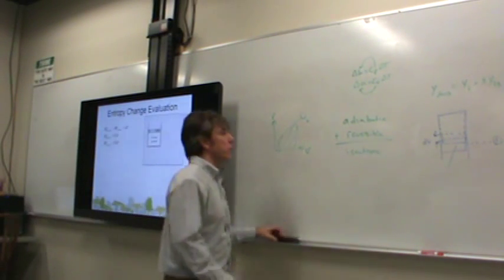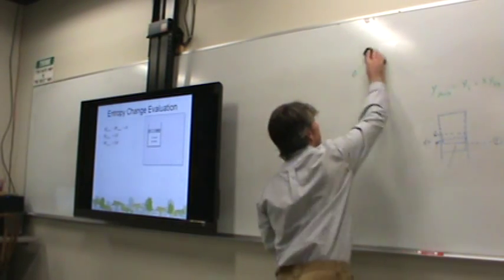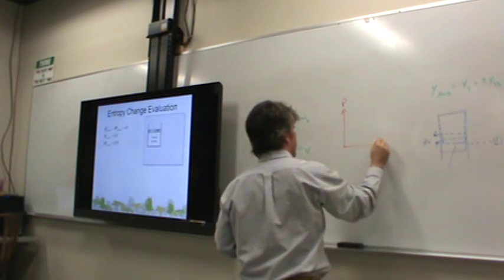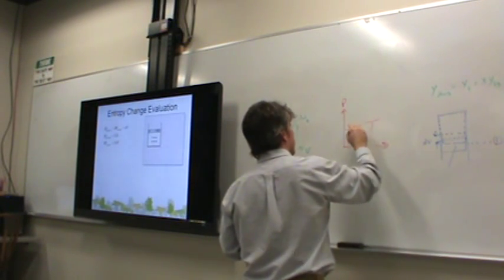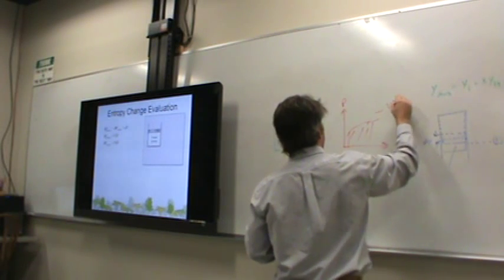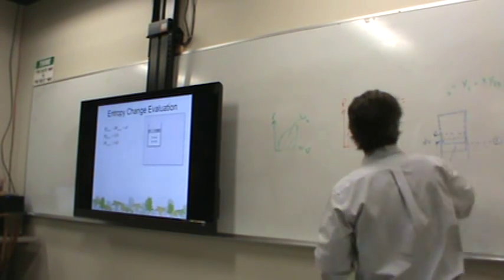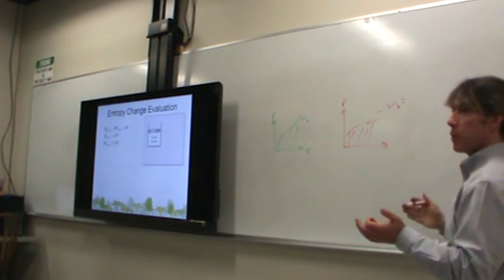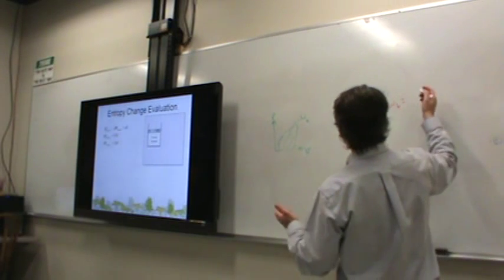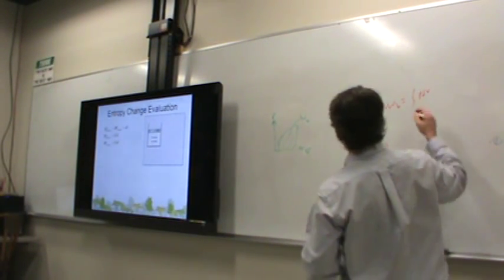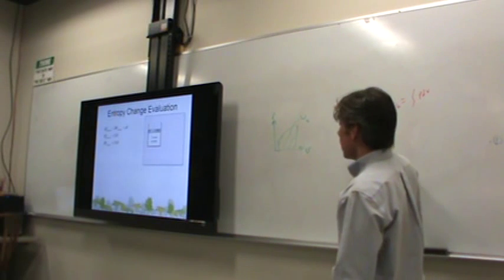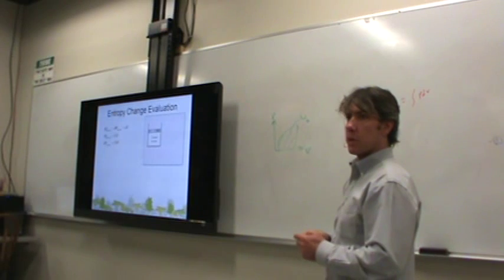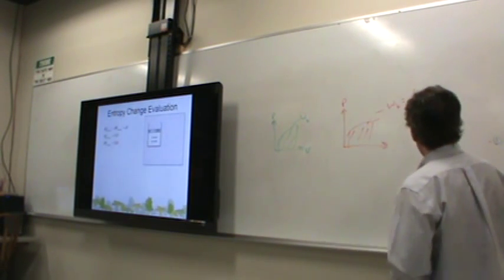Now be careful. I just said something that should have made you go, wait a second, I didn't realize that before. A second ago, I said on a PV diagram, the area beneath the curve represents boundary work. And none of you really questioned me on that because you've seen it before. And you were just happy that I didn't make you do much of the integration. Maybe I made you integrate once in homework. Because you were very happy to have the integrated form of PdV. But it turns out the area beneath this curve is only equal to the work if it's an internally reversible process.